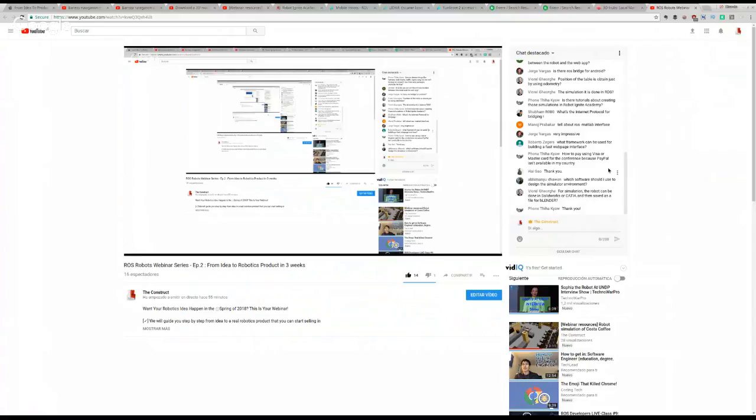And then Viral says, for simulation, the robot can be done in SolidWorks or CATIA and then saved as a file for Blender. Yes, actually, we have a very good tutorial that teaches you how to create a robot model in SolidWorks, and then transfer that with controllers, with everything, to the Gazebo simulation. So you can do it directly from SolidWorks into Gazebo.